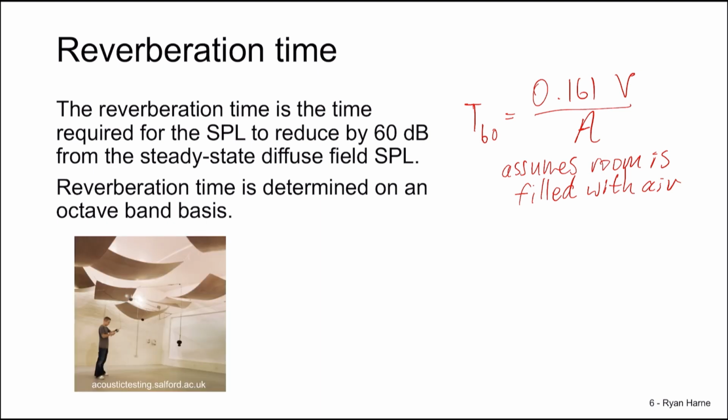To measure the reverberation time, it's best to be done in a highly reverberant room. Very often, these things are mounted on the ceilings called diffusers that help to create a very equal sound space where the sound energy is equally distributed in the room. Either someone claps in the room or another impulsive sound is released so that we can hear the decay of sound in the room.